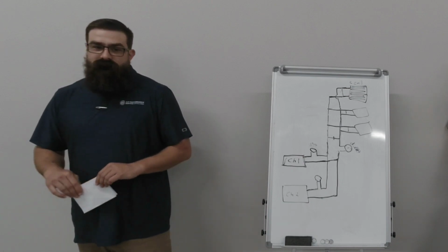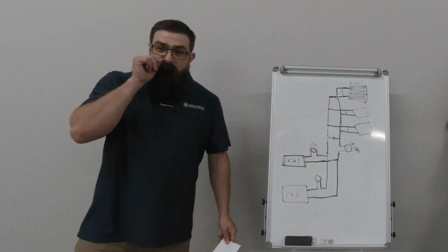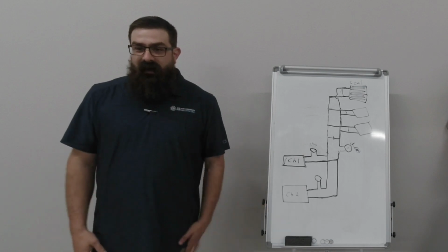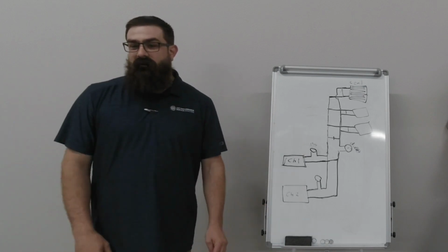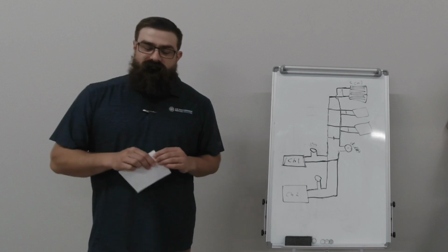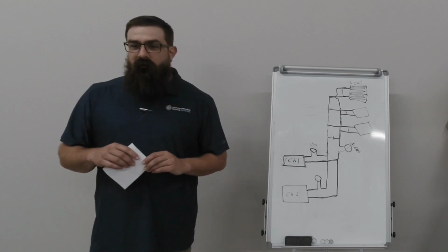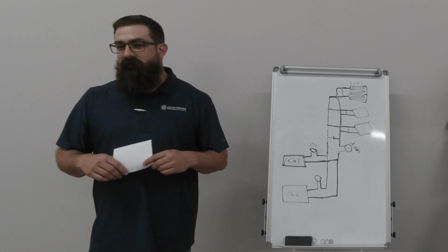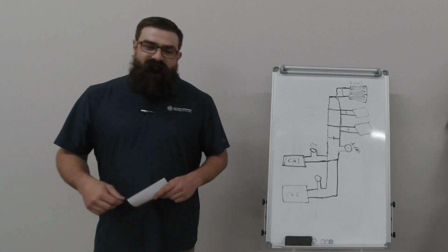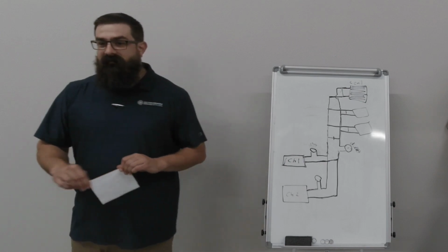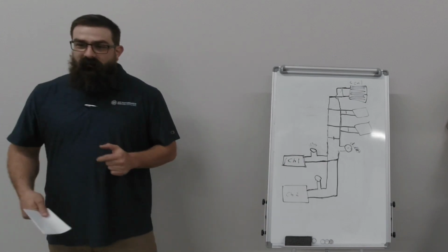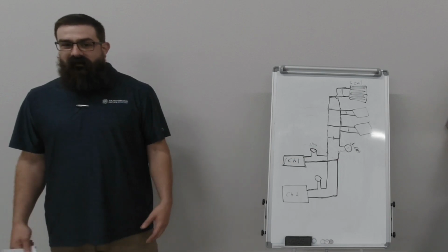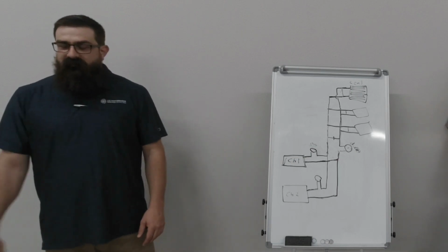Right. Anybody could do that. Well, that goes back to our entering water, leaving water, supply return thing. I've seen them mislabeled all over the place. I don't know what's what, so if you call me and say, hey, my supply water is this, I'm going to ask you, well, what are we supplying? So entering and leaving is the best. If you tell me, hey, my cooling tower entering water is 95 and my cooling tower leaving water is 95, I'll say, all right, well, is the valve open to the spray bar?